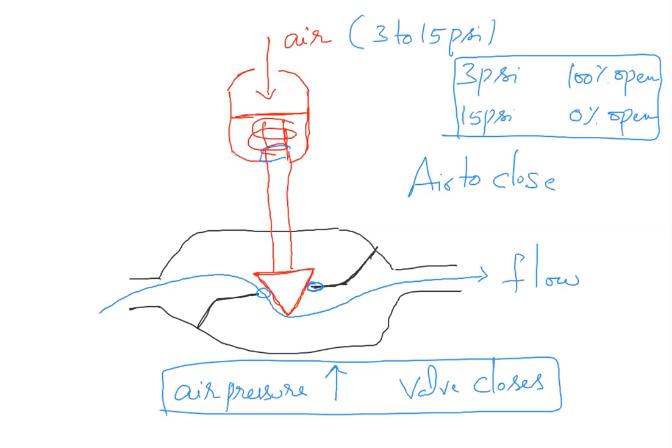Let's say the temperature of the CSTR is currently 60 degrees. How much cooling water flow rate do we need? We have discussed this problem. What we need is 1 ton per hour. For 1 ton per hour, the valve opening required is 30% opening.